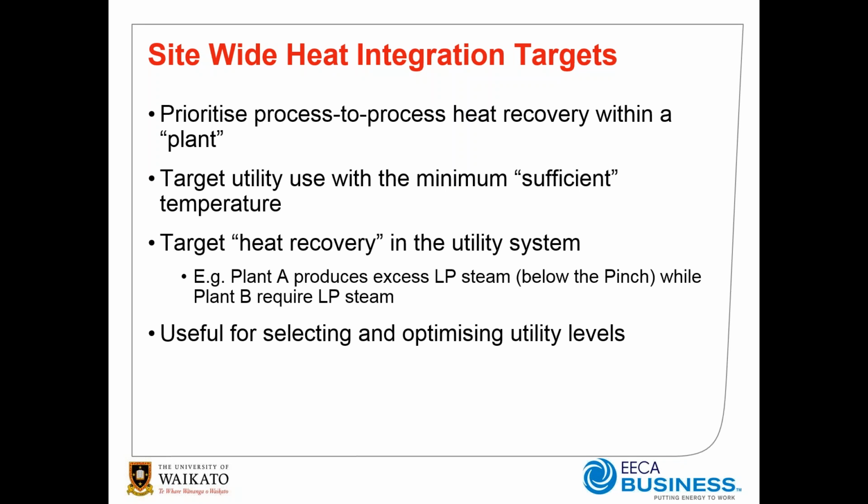We then can target the utility use for those zones. Now, I didn't talk about this today, but we can also apply this technique to look at what levels of utility we require for those process units. Then, once we analyze and look at the retrofits for each of the individual little plants, we can look at doing heat recovery via the utility system.